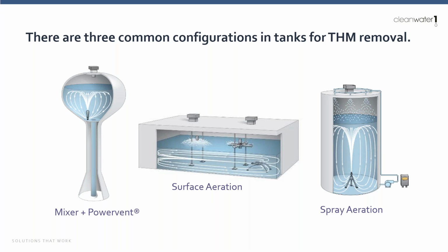And what this treatment technology, mixer plus power vent, really does is it takes the way that we usually think about water, water age is bad, the longer the water sits in the tank, the more problems I've got, and it turns it 180 degrees on its head. Now, the longer the water sits in the tank, the more treatment you get, and the better your disinfection byproducts are leaving the tank. So for those of you who are keeping your tanks partially empty because of concerns about water age, this will allow you to keep your tanks potentially full again. And that's important these days.